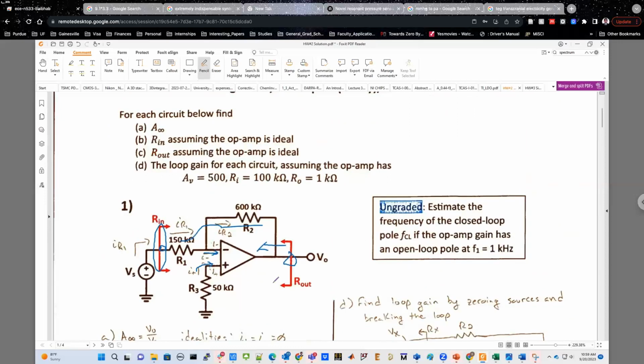What happens with the output resistance? Again, we have discussed this multiple times in the class: looking into the op-amp, you'll see a voltage source. The output of the op-amp is basically a dependent voltage source. So as you are looking towards the left into the op-amp from the output side, you see an ideal voltage source, because we said the op-amp is ideal. So what's the resistance of an ideal voltage source? 0. So in this path, you'll see a 0 resistance, and there is a parallel path which has some resistance, maybe R2, R1, and many other things can be connected into that path. But if you have a 0 resistance connected in parallel with some other, finite resistance, what is the equivalent resistance? 0, right? 0 in parallel with any other value will be equal to 0 in terms of resistances.